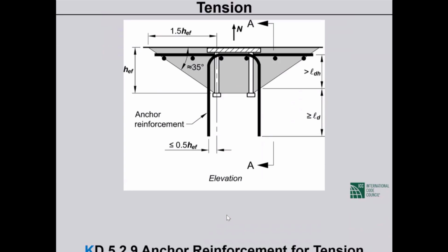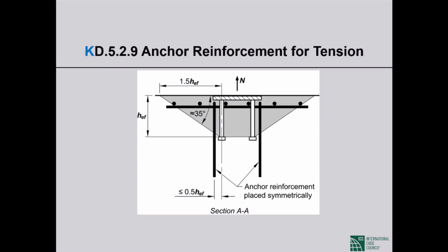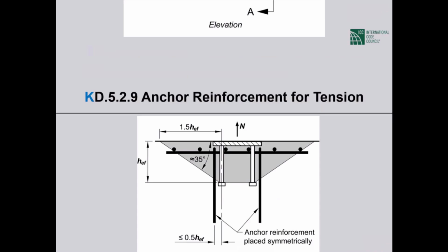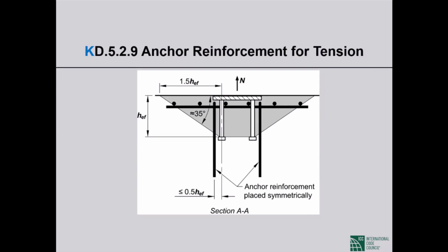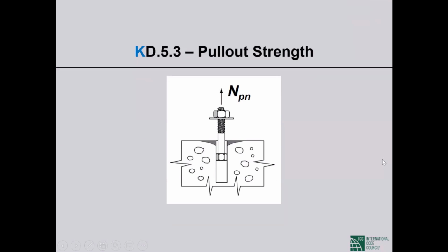So that was the front view that I showed you. This is the side view, the same group of anchors. This is the front stirrup, this is the back stirrup. We are looking at the same group. Now, we didn't run any numbers with anchor reinforcement, but I did want to show you the very powerful concept of anchor reinforcement.